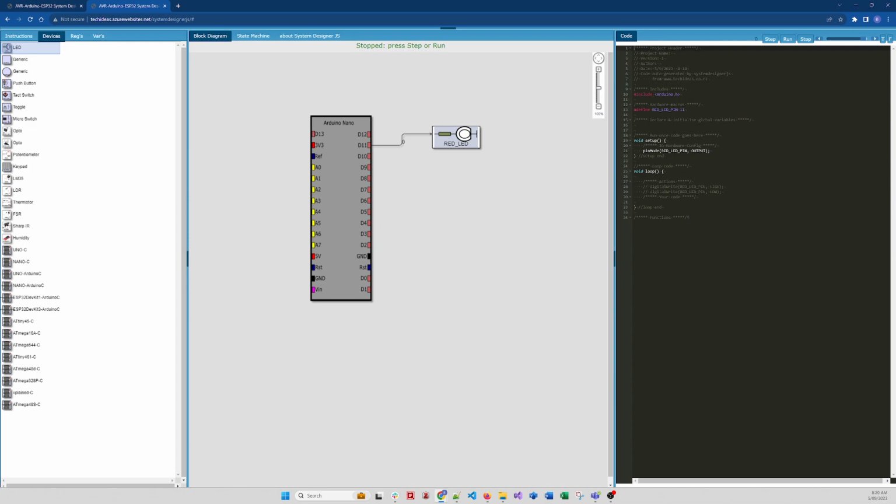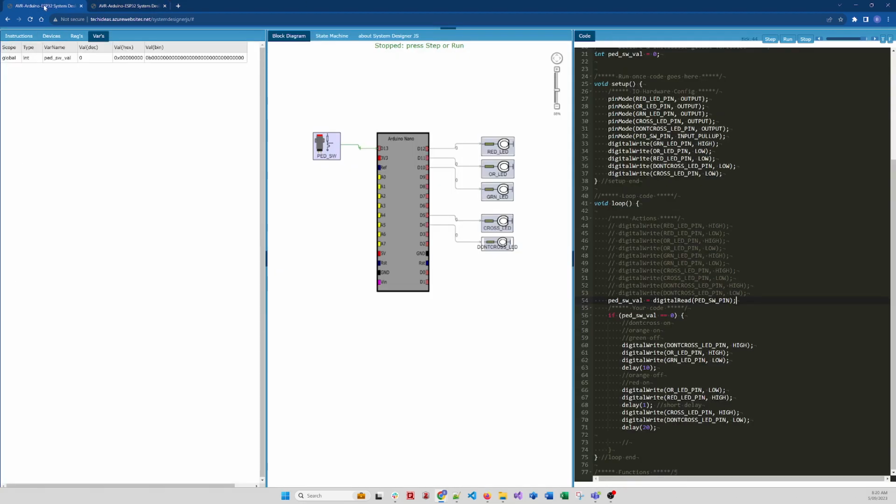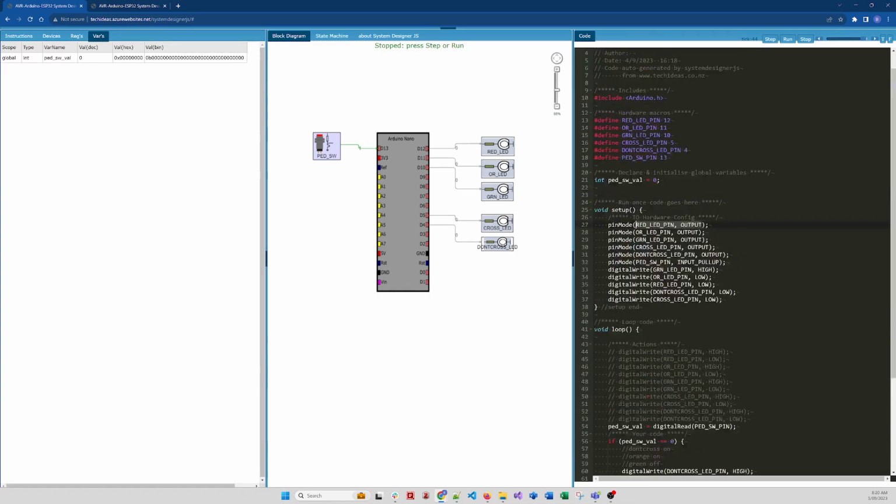Okay, and the first thing that needs to happen here is we design a macro to say, hey, red LED pin is the name of this pin here. It's actually 11. So red LED pin is how humans are going to refer to this, but 11 is how the microcontroller is going to refer to it. And you'll see in our program that when I run our program, these commands actually change to the values when I step it. If you watch, all these values here change.